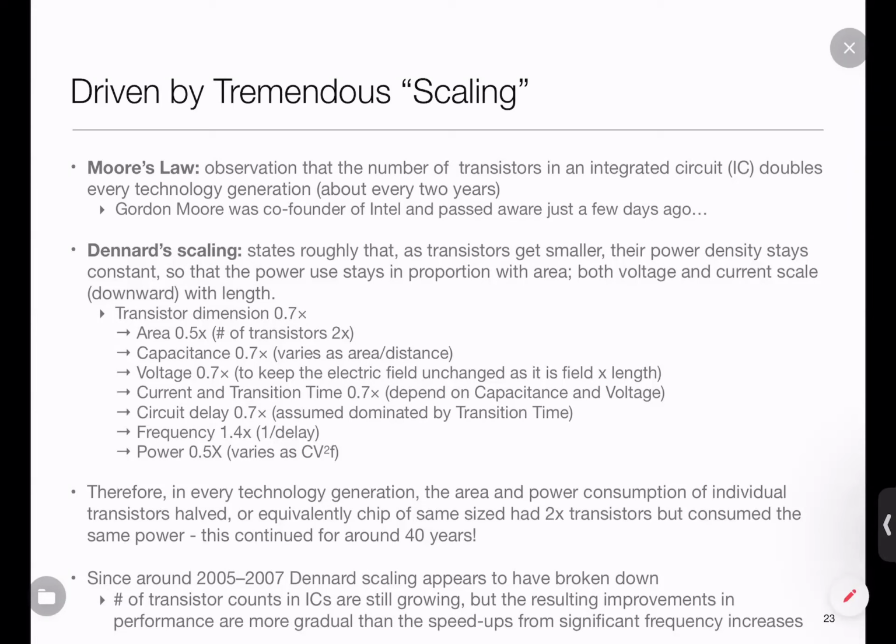So what that meant was that I can make big chips, Moore's law still holds, but I cannot keep all those transistors active at the same time. Because if I were to keep them active, actually doing computation, then the chip will burn itself out. So while I can put in more processors, I cannot have all those processors active, or alternatively, I need to run them at a slower frequency.